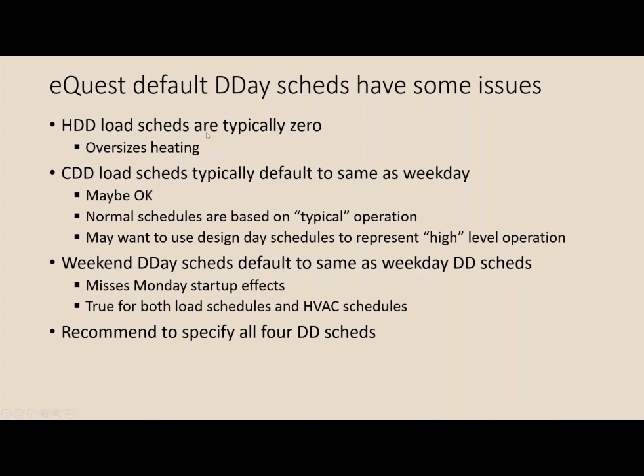On the other hand, there are some code types of requirements for doing simulation-based code evaluations that specify the heating loads to be 0 in certain jurisdictions. So you may find that that's what's required, but if you're actually trying to match what designers would do or what the actual building is, you may want to look at something besides 0 heating degree day load schedules.